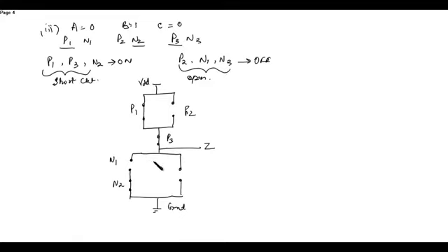Now over here, N1 and N3 block the low voltage since they both are open circuited. In the PMOS, P1 is short circuited, P2 is open. So since P1 and P2 are in parallel, this open circuit will not affect. Since P1 and P3 are in series with each other, this is short circuited, then this is 1.